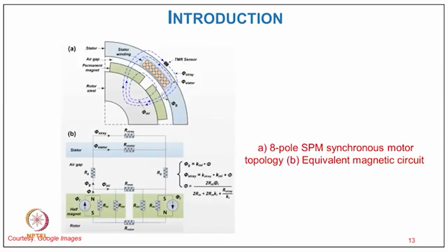These are typical examples, and here is a further example. Look at a surface mounted permanent magnet synchronous motor, its actual physical geometry with the conductors and the magnets placed on the surface of the rotor, and how the flux lines flow into different parts. You can even measure the flux outside the stator core, and see how it is represented in the equivalent circuit. The magnet equivalent we put as a flux source for excitation, with a parallel reluctance, and then we have the reluctance of different paths.